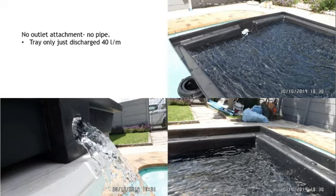The one hose pipe comes directly from my mains. Granted, it's an oldish house and the mains are 1/2 inch. But the other hose pipe comes from my tank and booster pump. So I had to switch both on, and I had to throttle the mains just ever so slightly to achieve 40 liters a minute. And you can measure 40 liters a minute quite easily through a 10 or 20 liter drum, time how long it takes to fill up, and you do your calculations from there.